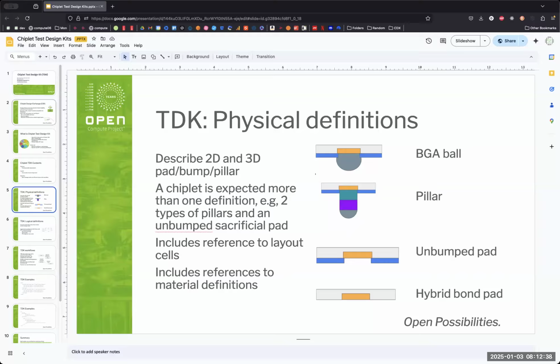Right. Yeah. It's only an intermediate step for wafer probe. The difference is really that the data kind of splits. When it goes to manufacturing, you derive the sacrificial pads when you ship the final product. You really don't have to define the sacrificial pads unless you want to let your customer test your dies. Right. Again, that's a workflow type of a question. And we wanted to stay flexible and to allow that.